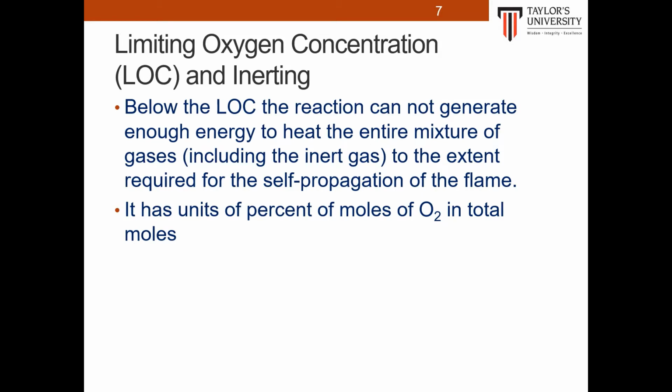The LOC has units of percentage of moles of oxygen in total moles. If experimental data are not available, the LOC is estimated using the stoichiometry of the combustion reaction and the LFL. These procedures work for many hydrocarbons.